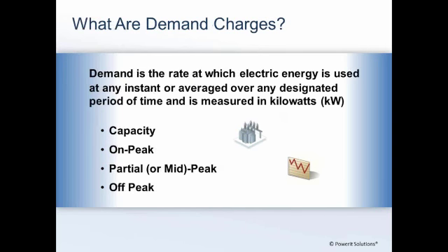So to give you a little overview, off-peak is the time of day when power is the cheapest for the utility to produce. The capacity is the amount of capacity the utility has to have based upon your highest usage. The on-peak is generally set up during the high-use time periods. This time of year, it would be falling into the late afternoon, early evening time period because of heating and lighting and it getting darker out. During the summer, it would be more midday because of air conditioning load.